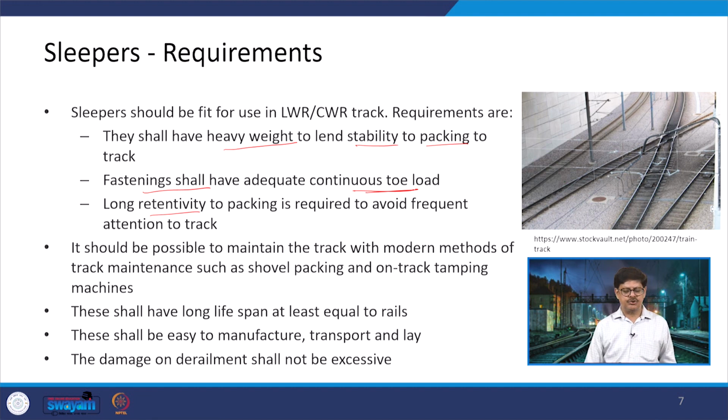Other things are it should be possible to maintain the track with modern methods. Nowadays we are using various machines. There can be shovel packing or an on-track tamping machine. So, it should not happen that when those machines are working, either we have to remove the sleepers or, if the sleepers have been placed in position, they get damaged. That should not be the case.